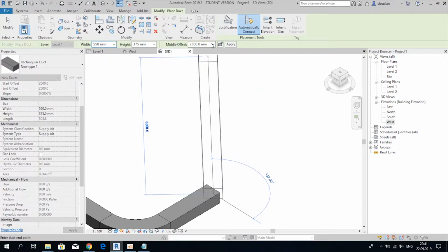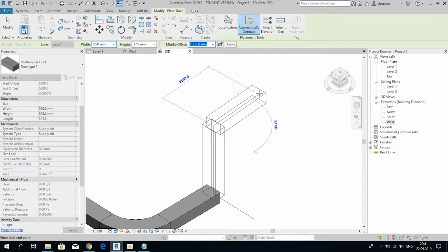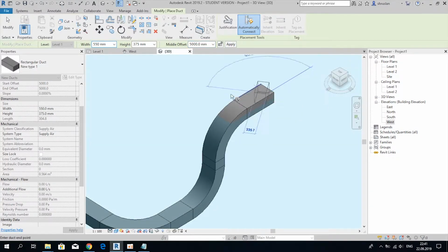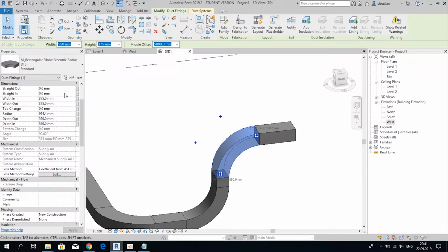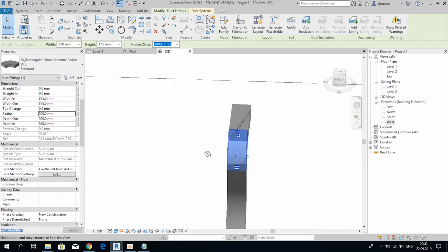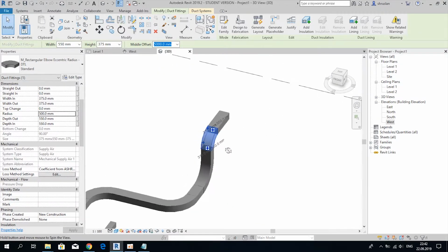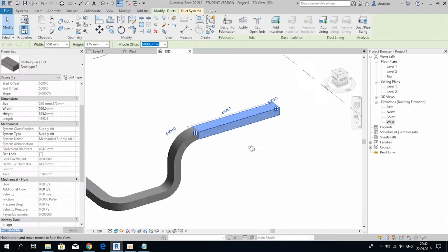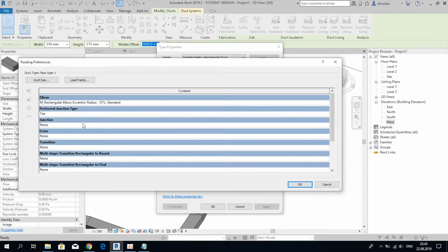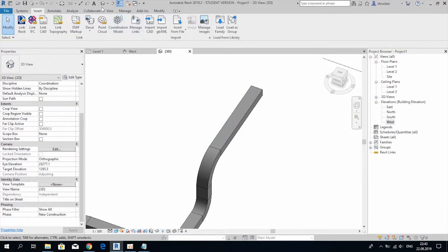If you want to create the vertical section, we should select place and the first elevation. We can change the family instance parameters of elbow in properties, for example, radius. We can change the parameter for all at once. Let's load the T and set the T for a type like elbow.